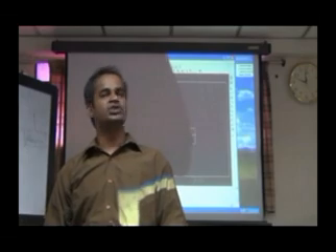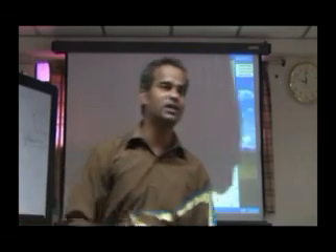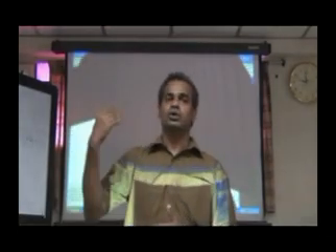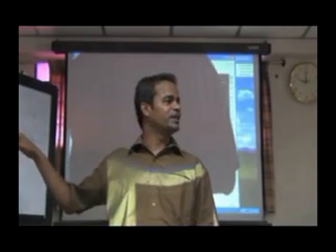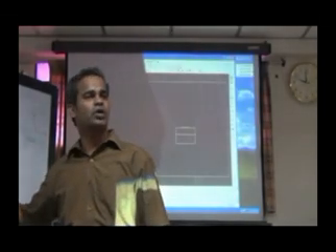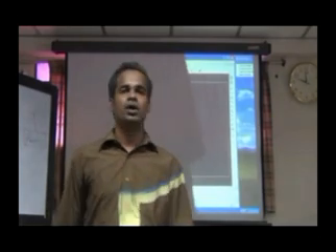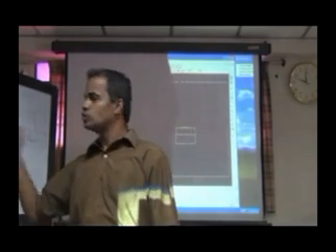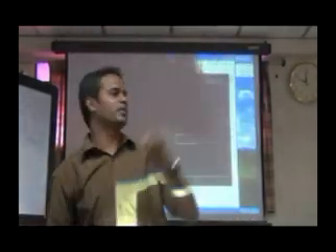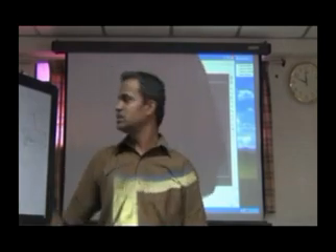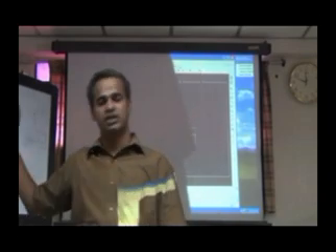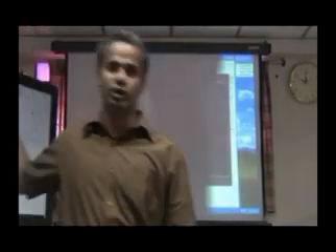If I am able to give all these inputs, it will generate the part program itself. So I need not write the program, I need not check it. The part program is generated in CAM. CAM is nothing but part programming generation. It will generate a part program according to your requirement and according to your machine, whichever machine you want. That program I can push to the corresponding CNC machine, and it will manufacture and give you the component. That is nothing but CAM. So part programming also we need not do; it can be generated using the CAM module.